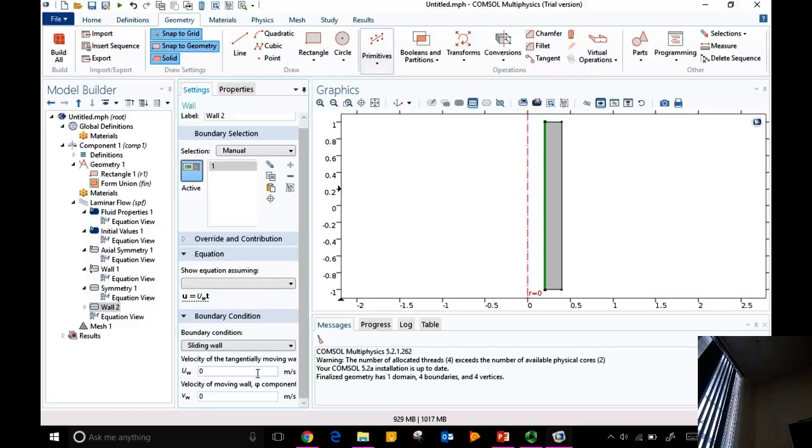So this is gases in catalyst pores, nanopore size scale. Then you will have Knudsen diffusion and you will have slip at the wall. The other example that we talked about is when you have long polymeric chains where the length is fairly significant and one end gets stuck, the other end is inside, then it exhibits stick slip kind of a phenomenon.